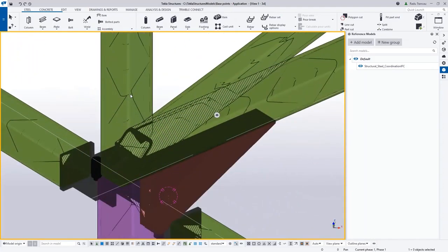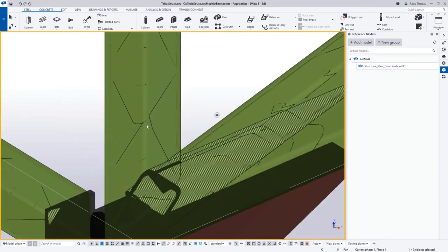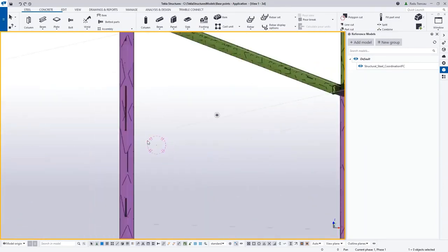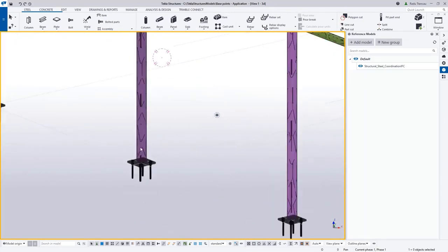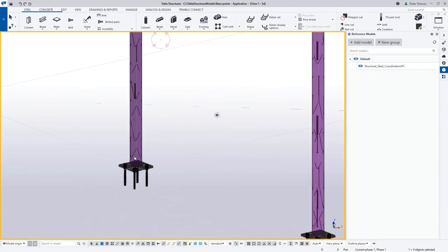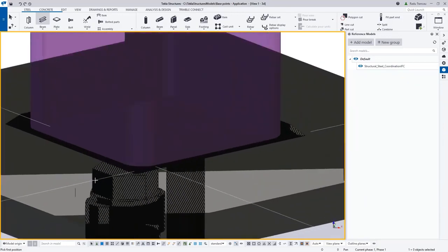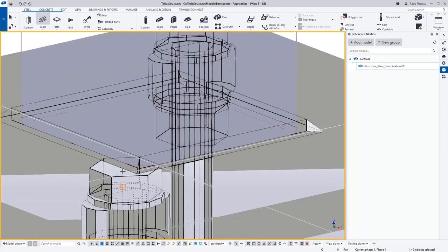So what you'll see is, if I zoom in, the solids will start to lose accuracy. It will become very pixelated, and it will become very, very hard to work with snapping. So let's, for example, try to create a beam right now. If you want to snap a beam, for example, I will just move into this mode.